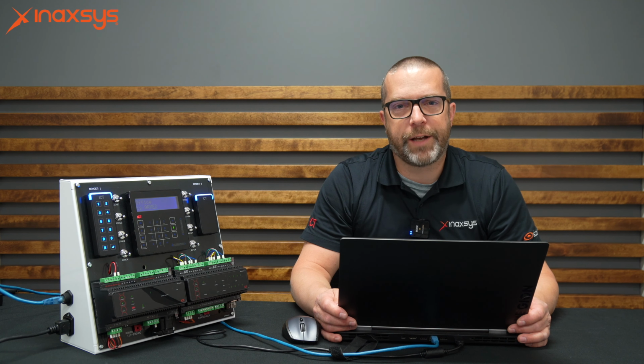You just need to set the control output time to the number of seconds you want. In this example, I'm using 2 seconds. All right, the minimum is 1 second. And then the control output will be keypad 1 beeper, which is here on my kit. Okay, that's basically it. Now also there's under options 2, under the output activation options, you have activate control output on alarm.